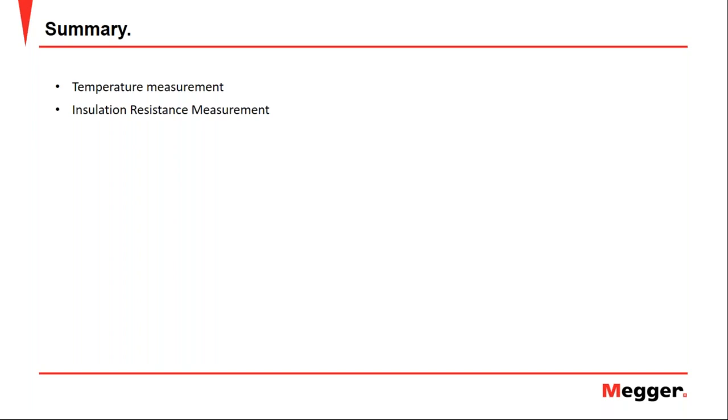After performing the insulation resistance test at the voltage level suggested by the standard, we must make the correction of the resistance value to 40 degrees Celsius and compare it with the limit established in the standard. This is only in the case the manufacturer doesn't say otherwise.